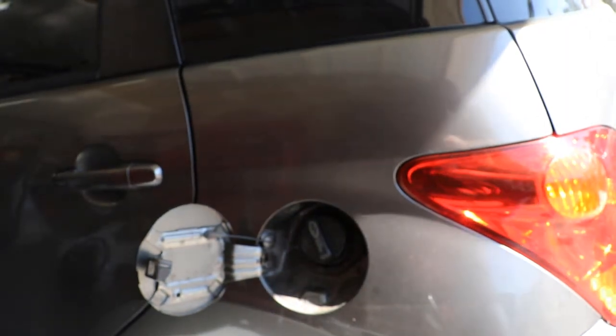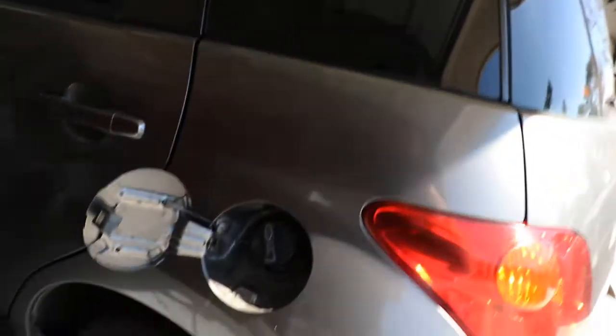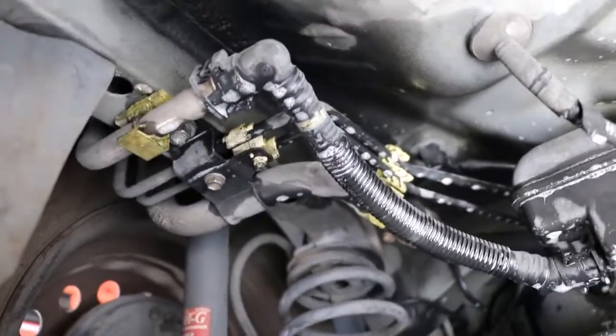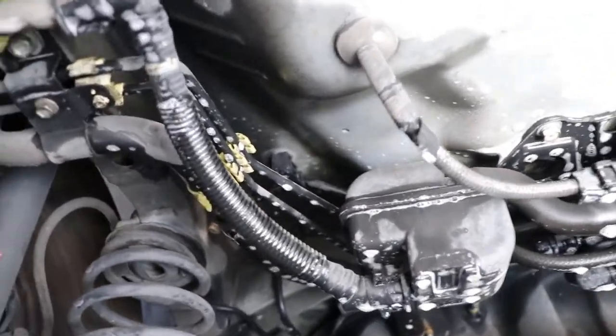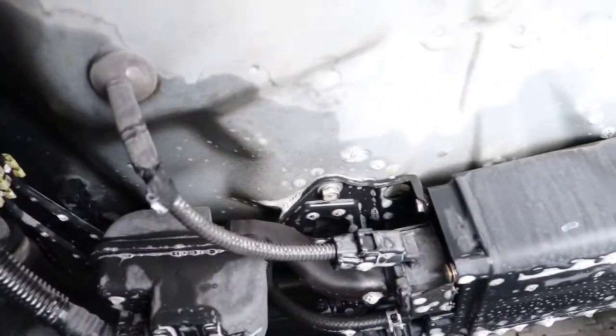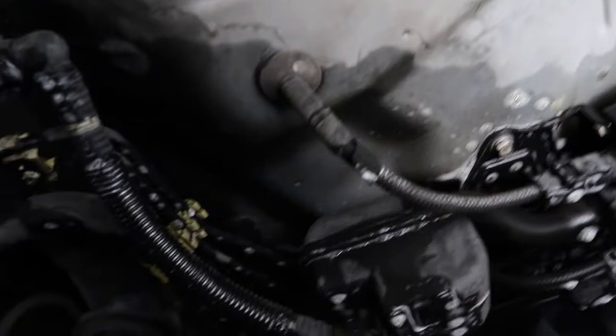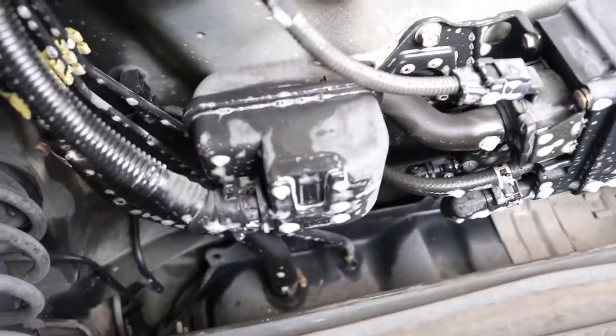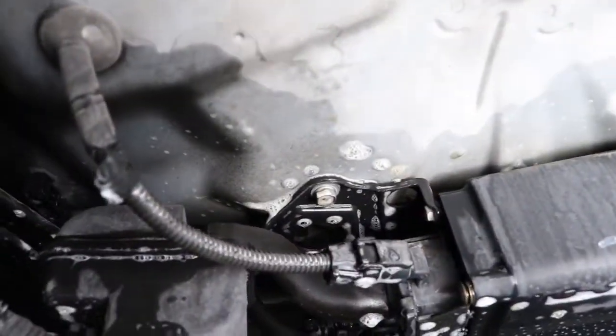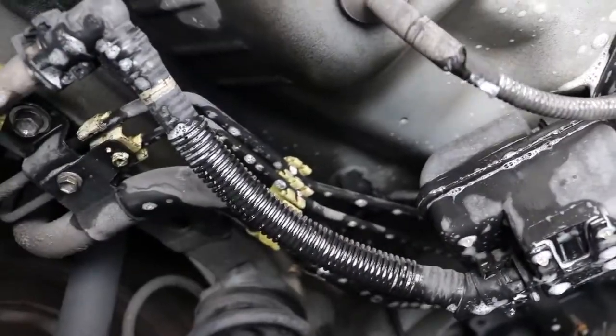Now the next step I want to do, and actually I've already done it, is I've come under the car, and I do have a bottle of very soapy water. So if you don't have a smoke machine to check, I put soapy water, just Dawn dish soap, and I sprayed all of the components here just to detect for any leaks, any bubbles, and there was no air escaping, there's no air getting out of anywhere. Everything looks pretty good, and I will be washing this off just to confirm. And I did go underneath the other side and inspect all these hoses, and everything seems pretty sealed tight.